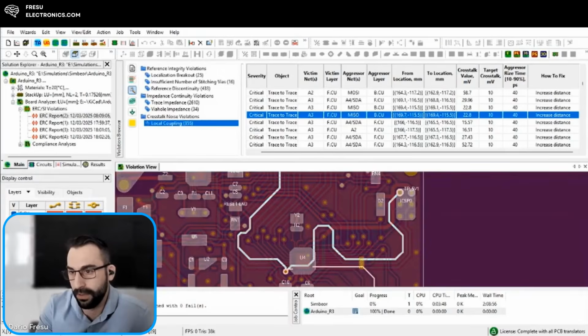Now I show you with the software, but you can check them even without the software to have an initial understanding. Because with the software, it's faster. It takes you 5 minutes to have the result, the report, you print the report. Okay, this is what you need to do. Now, if this is a $1 million project, suppose that this board is not passing the EMC test. They contact you and they say, look, I need an EMI specialist. They check my board because I cannot pass the EMC test. I try multiple times. I don't know what to do. You plug it in here. In 5 minutes, you have already most of the issues that you need to fix.